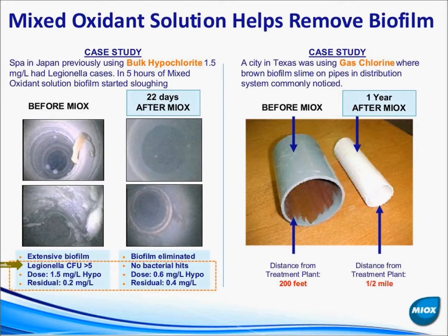And as I think most of you realize, disinfection byproduct formation is really a combination of three things: the concentration of your organic precursors, the concentration of the chlorine, and the time involved. So if you can reduce any one of those things, you reduce either, as I mentioned, the concentration of the precursors. If you can reduce the chlorine concentration, you normally don't have a lot of control over time. So the two things you have to focus on are those two things. And by cleaning up the biofilm, you certainly address the chlorine aspect of it, as well as the carbon precursor aspect of it.